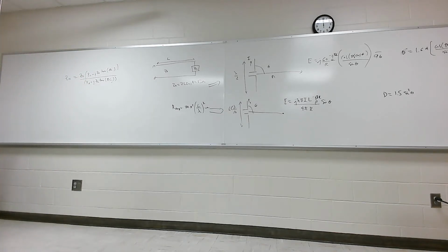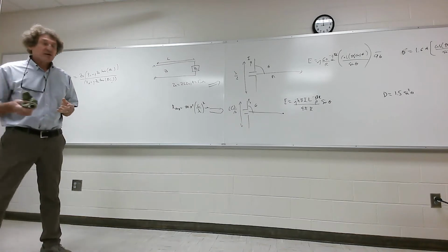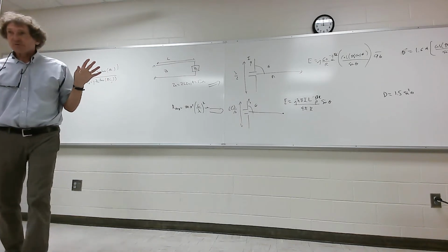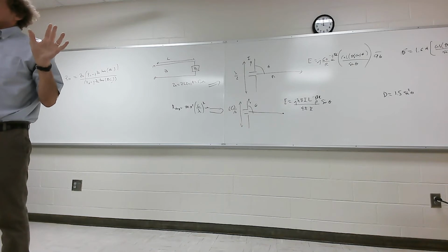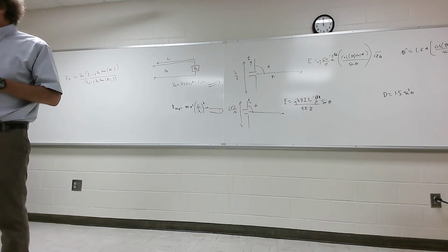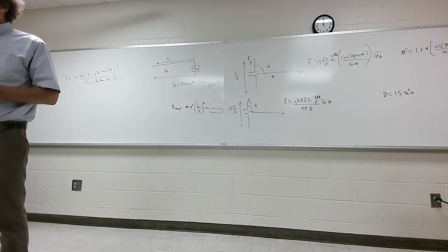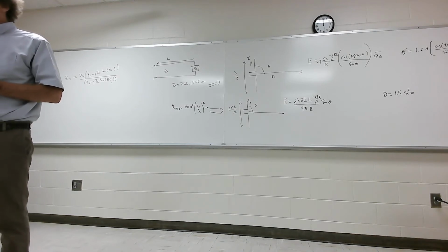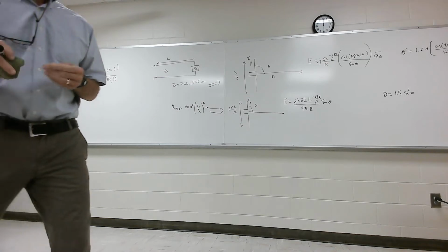Another way to do it, and this is not a good way, is just put a capacitor in series that would have the same reactance, only minus J 42.5. That would get rid of it too. There's two ways. But that's an additional element, and in the real world, you never add anything you don't absolutely have to. You try to minimize costs, and the more components you have, the more things that can go wrong, especially in high power stuff, because then you get a lot of failures from heating.